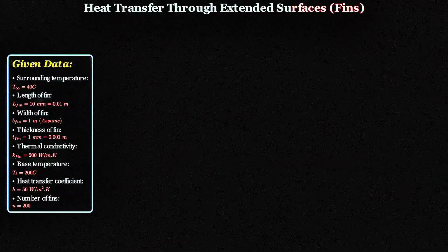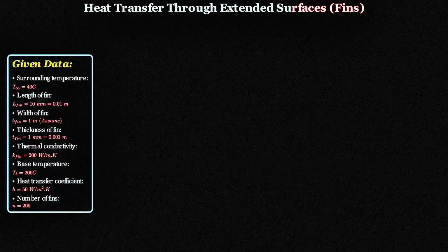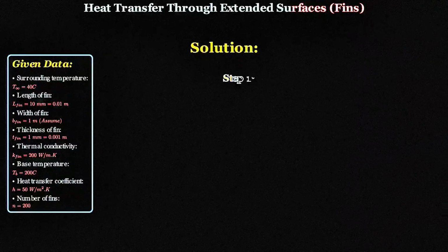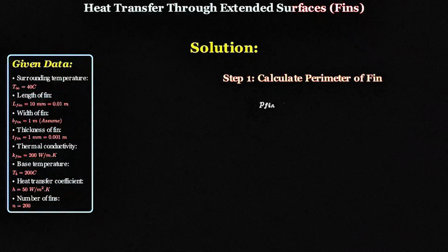The heat transfer coefficient, h, is 50 watts per meter squared Kelvin. And the number of fins is 200. Let's work through this problem systematically. Step 1. Calculate the perimeter of the fin.